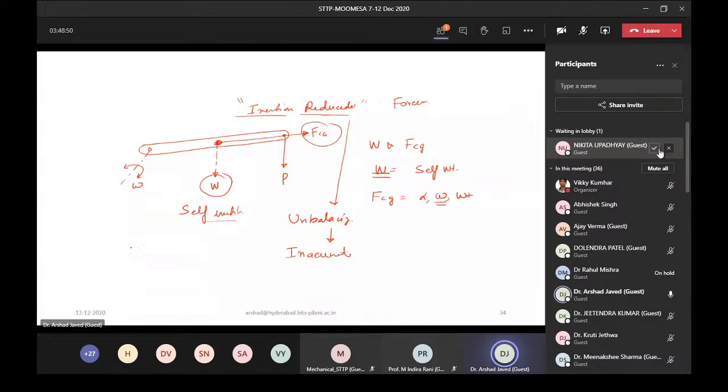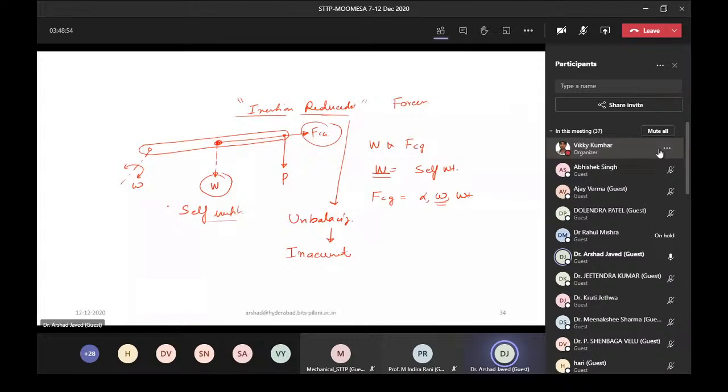Let us see in a physical way. If we take this big rod and try to rotate it with a high velocity and it has to stop at 30 degrees, what will you face here? This fellow will not stop at 30 degrees but try to move ahead of 30 degrees. So we have to put mechanical brakes here so that it can stop immediately. And when it stops, it vibrates because of high inertia. It vibrates and then stops. So these are the effects of a larger inertia value, and that is because of high self-weight.